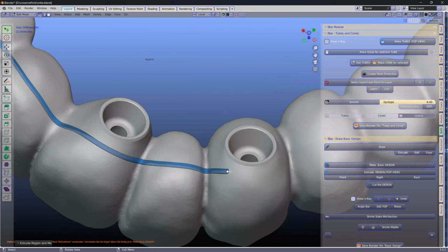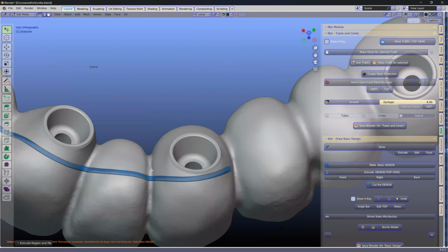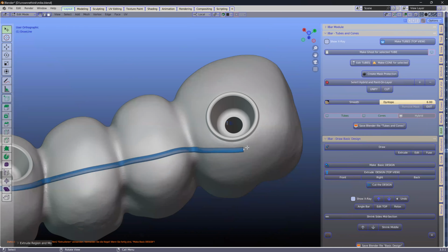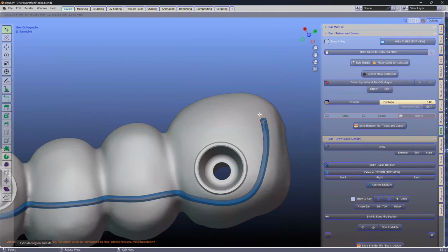If you can smooth those down as much as you can, that will help prevent any failure. I'll demonstrate in a minute why I'm saying that. Here I want to make sure that I don't have sharp edges, so I don't want to see something like that. We want to keep everything nice and round, and smooth. Everything's smooth.